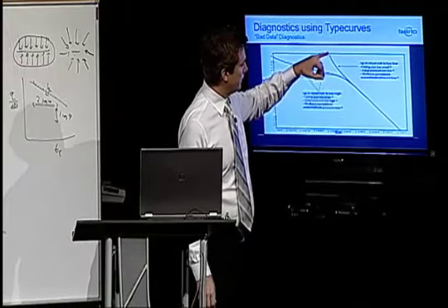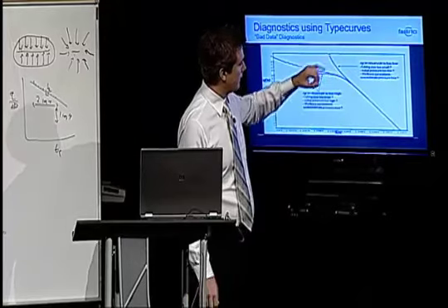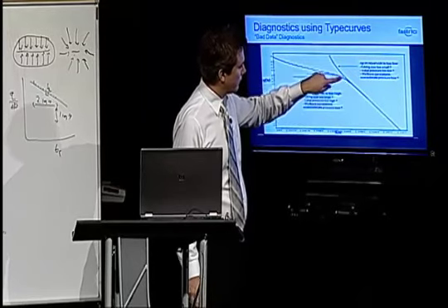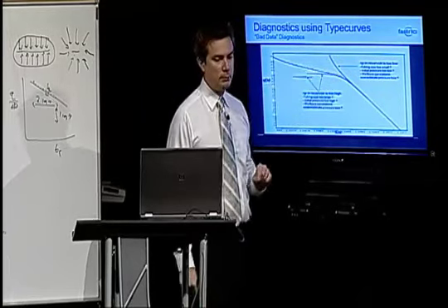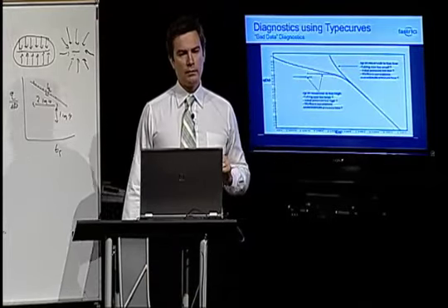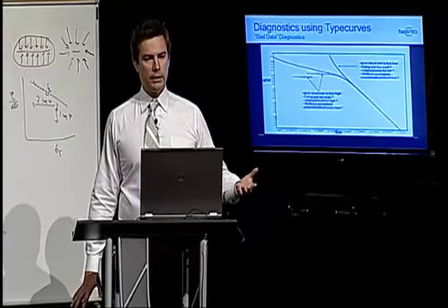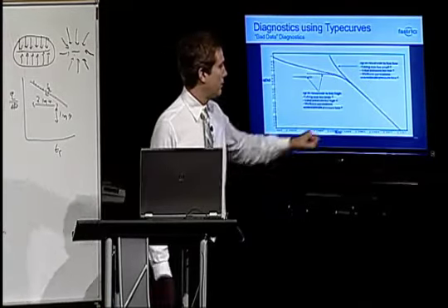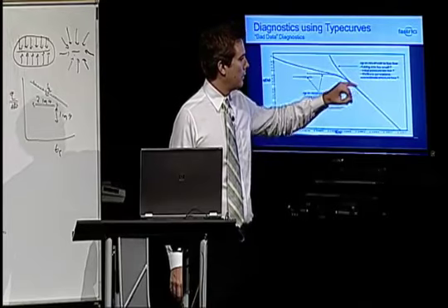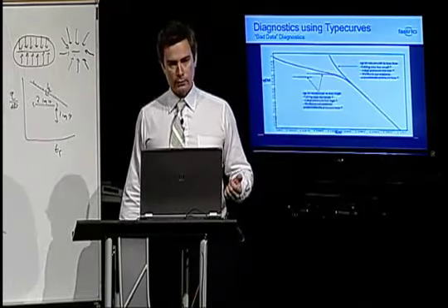In the other sense, we could end up getting a shape of the data that looks like this. There's no reservoir effect that can cause that steep of a drop at the beginning. If it looks like this, it means that your delta P is off somehow. In other words, your pressure loss in your wellbore has been over-predicted in this case. So maybe the tubing was made too small, or the initial pressure was too low, or the wellbore correlations overestimate pressure loss.